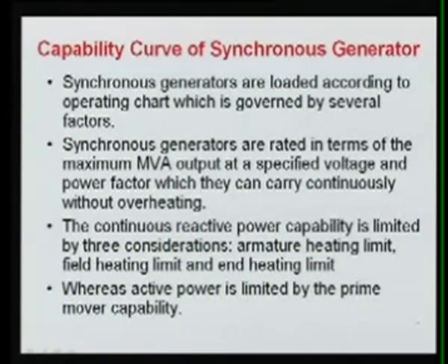Today we will see what the capability curve of a synchronous generator is, and that is true whether it is a salient pole or a cylindrical rotor synchronous generator. Synchronous generators are loaded according to the operating chart, which is governed by several factors. We cannot increase the voltage beyond a limit, and the loading of real and reactive power also has to be limited.